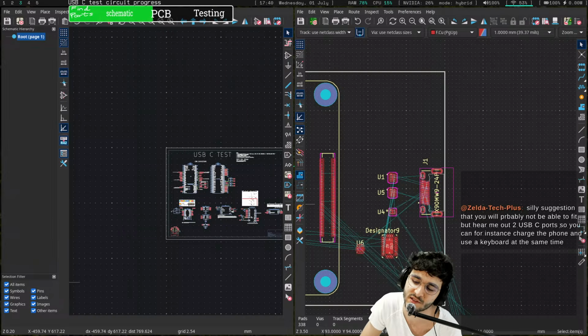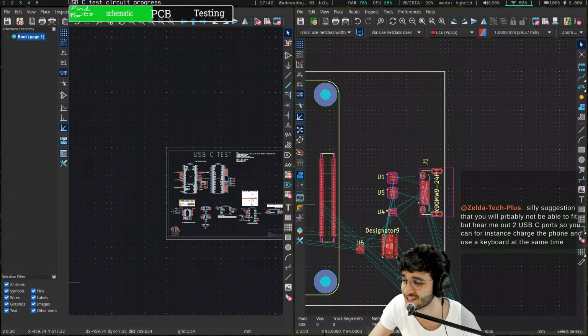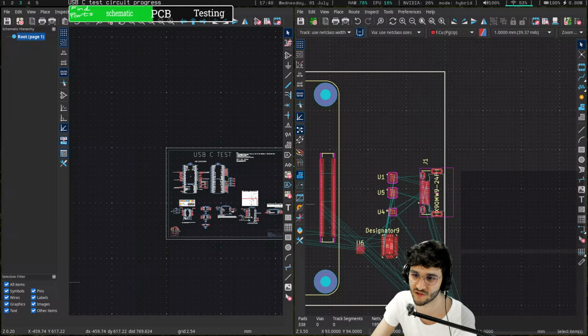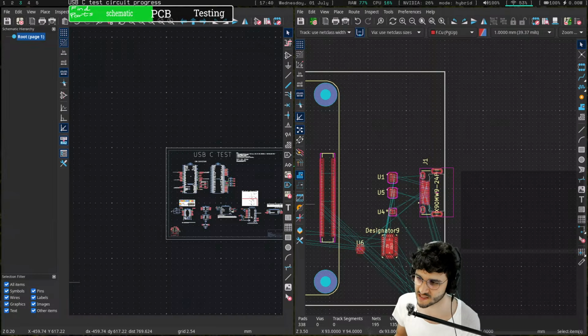Isn't it easier to use a USB hub than to have 2 USB ports? I think the USB schematic is complicated enough because I cannot imagine how to solve having 2 USB ports that are both functional. For sure they cannot work at the same time because the CM5 only has, I think, one USB 2 data lane and only one set of USB 3 lanes.